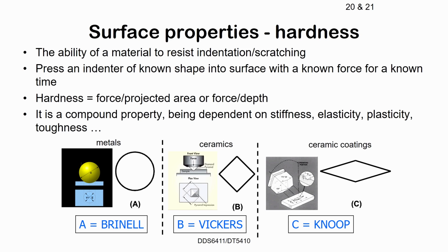indentation. So it depends on everything that we covered. It depends on the stiffness, right? The stiffer the material, the harder you have to press on it. It depends on the elastic limit. You have to bring it beyond the yield point. So it's a compound property. It depends on all these things that we've just covered.